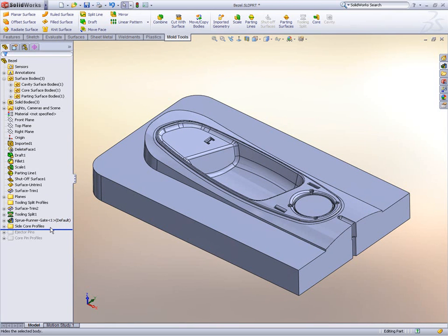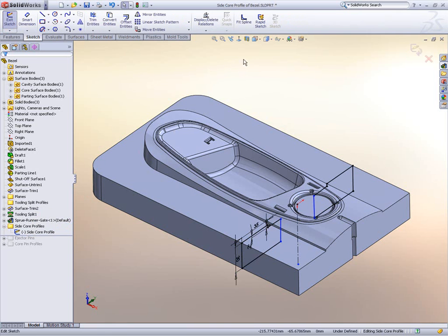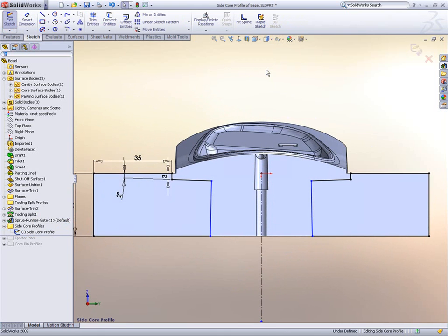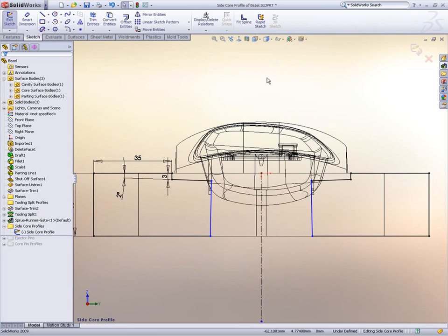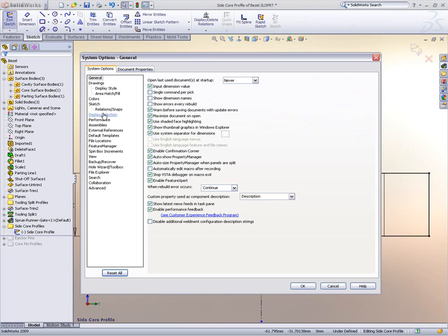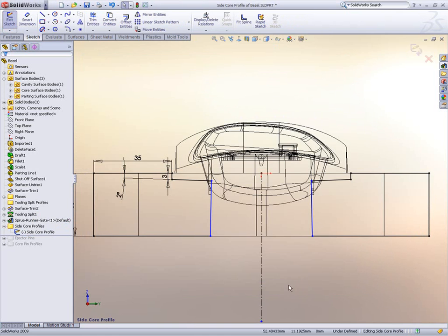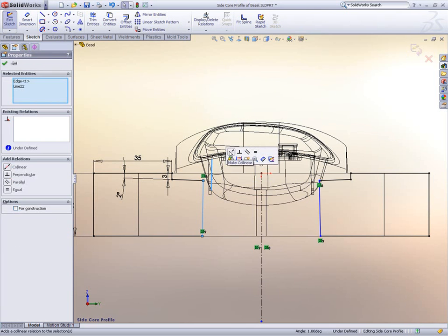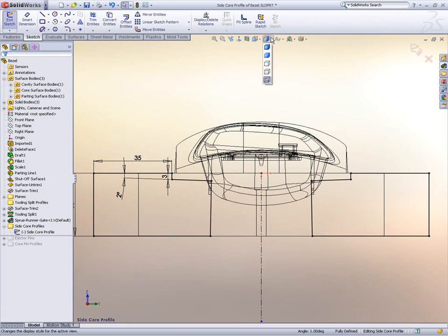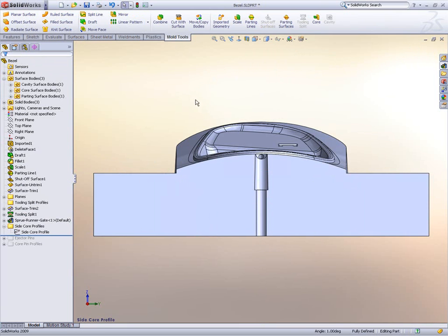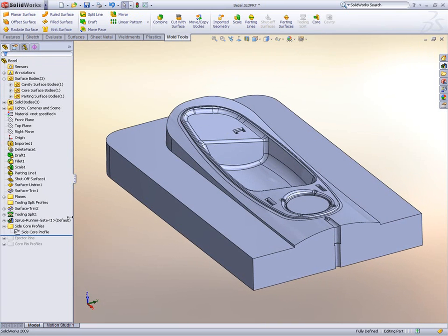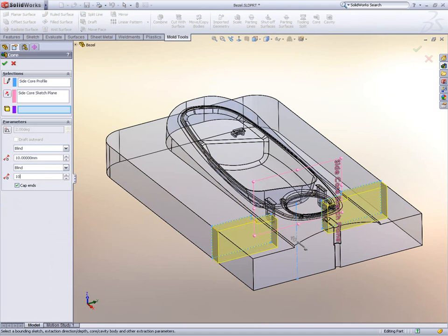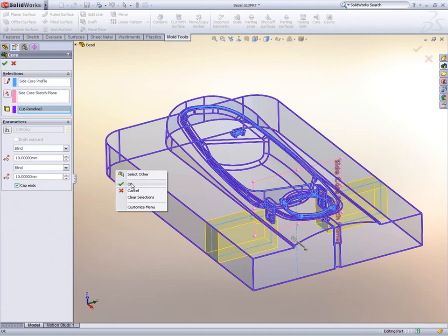The undercuts on the snap fit features will need to be removed with a side core. Again, we have a sketch provided, which we just need to edit to attach it to the geometry. Turning off the shading is a quick way to see the hidden detail. Once done, the core feature creates the side cores and the corresponding cutout in the mold core at the same time.